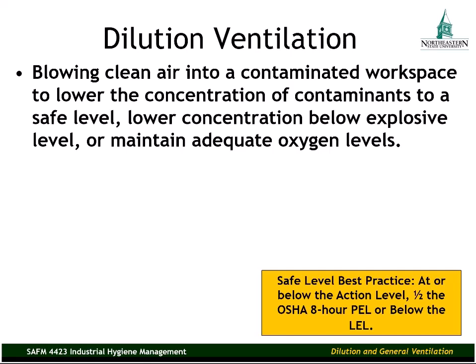With dilution ventilation, we can go well below 1/2 of the PEL or 1/2 of the TLV in a lot of cases. Also, if we're talking about flammable vapors or explosive vapors, we want to be below the lower explosive limit. Normally, we want to be well below the lower explosive limit, maybe like 10% of what the LEL value is for the particular substance.